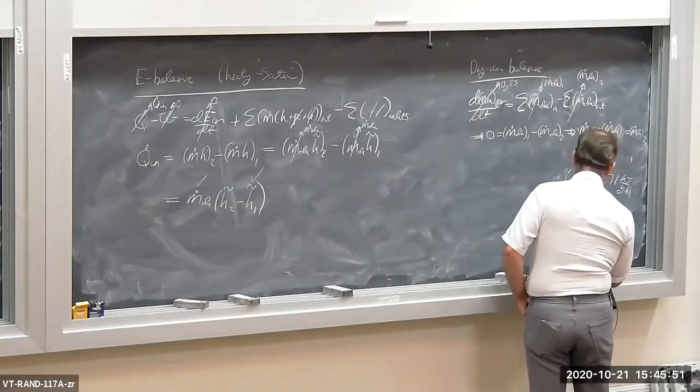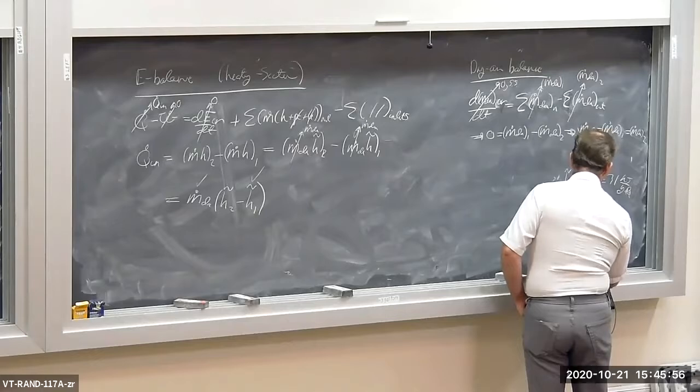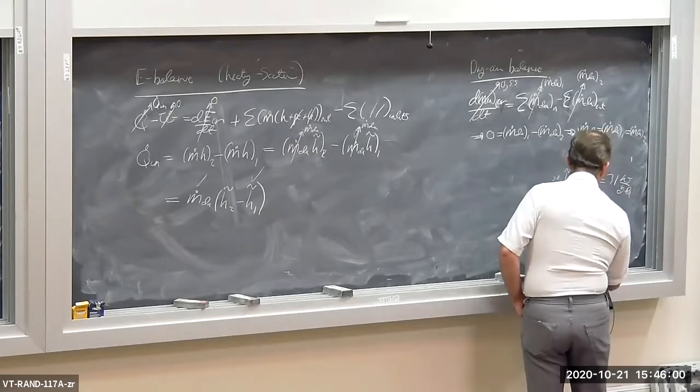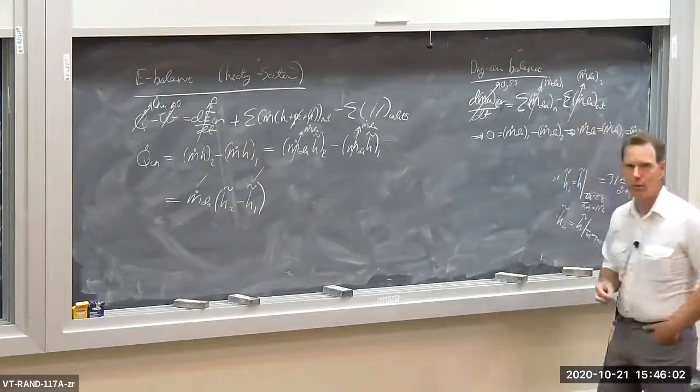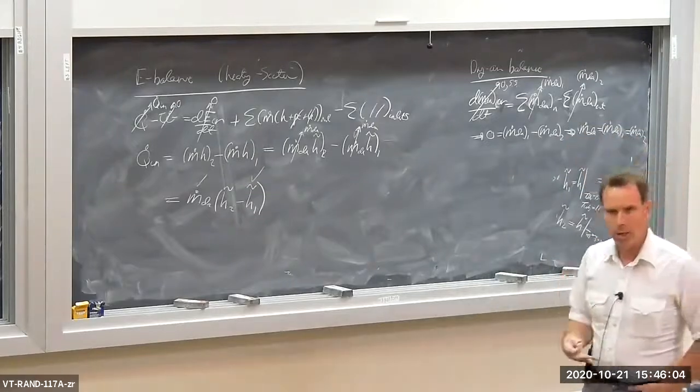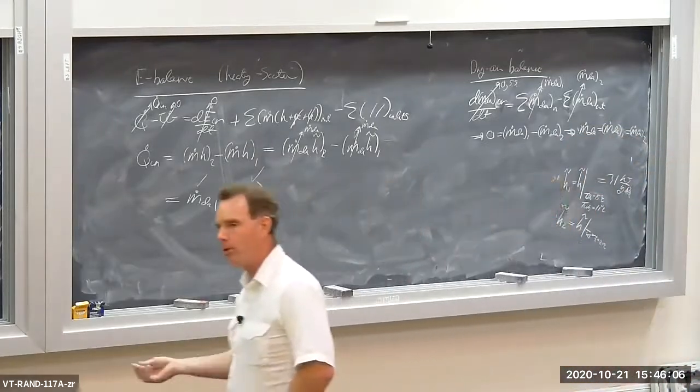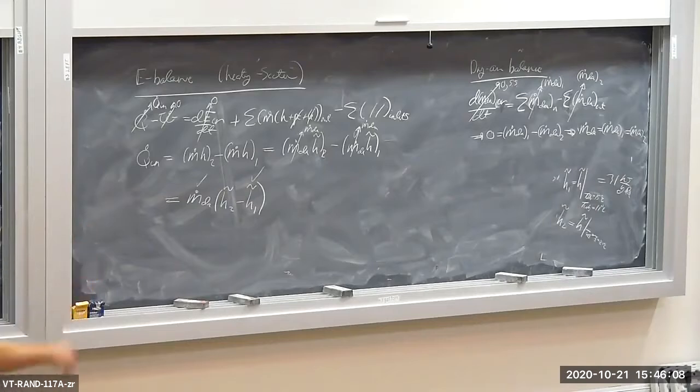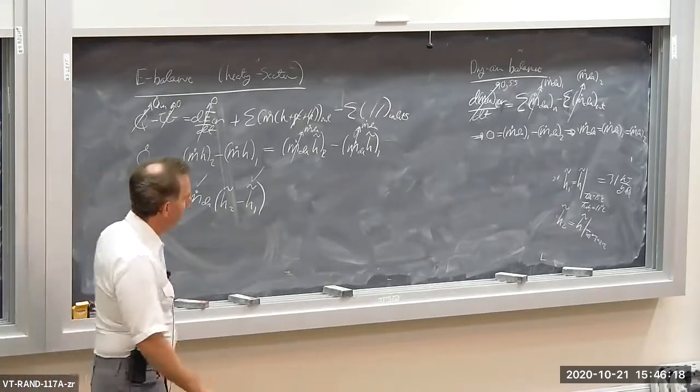So I do know that the dry bulb temperature is T2, and that's 20 degrees C. I need something else. I need a relative humidity. I need an absolute humidity ratio. I need something to get a second property so I can find the state, okay?